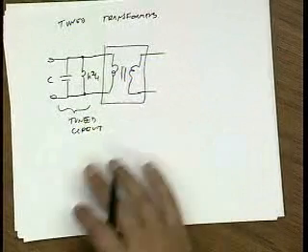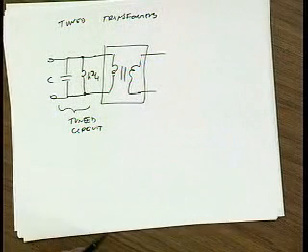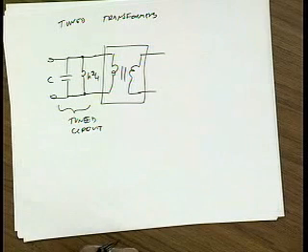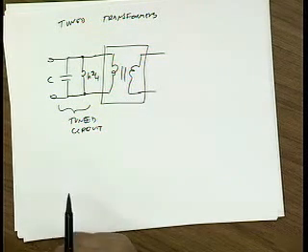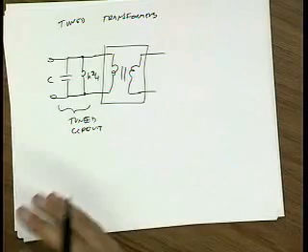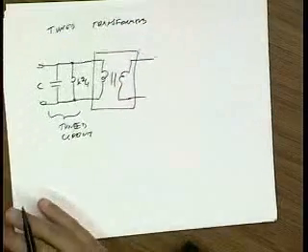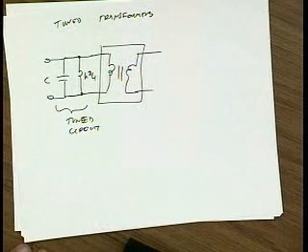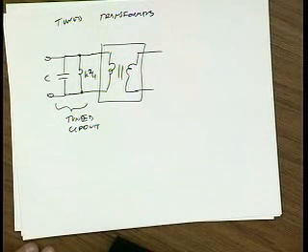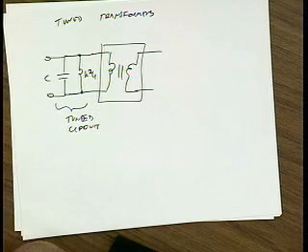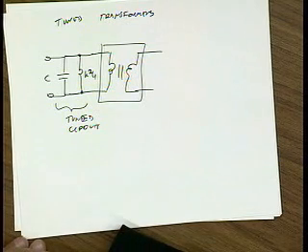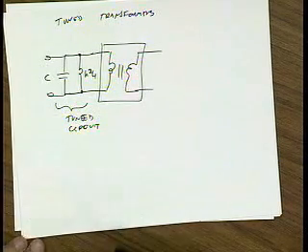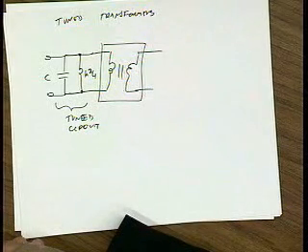Questions about transformers, Firas? Transformers, but about mixers, I mean, up to what frequency can you use the mixers that we have demonstrated? That's actually a really good question. Nobody has derived a nice, beautiful equation that says if the FT of the transistor is this, this is the highest frequency you can use the mixer. Most of it is kind of intuition. You build mixers, you have experience with them. But certainly, most mixers would operate at about FT over 5, FT over 4. That would be kind of a loose limit. And conversion gain starts dropping considerably if you go higher than that.